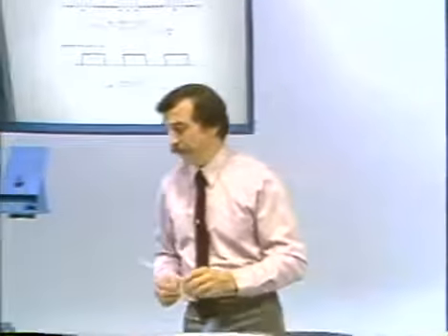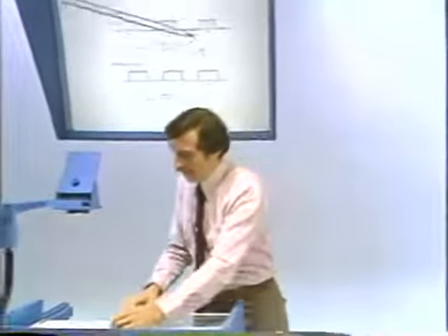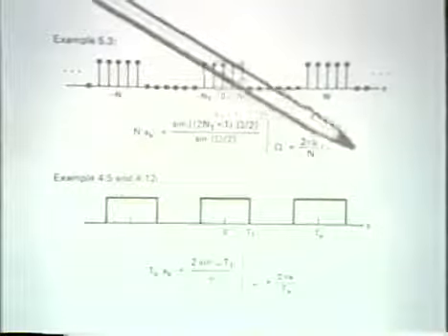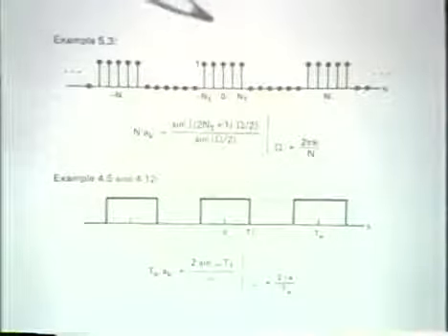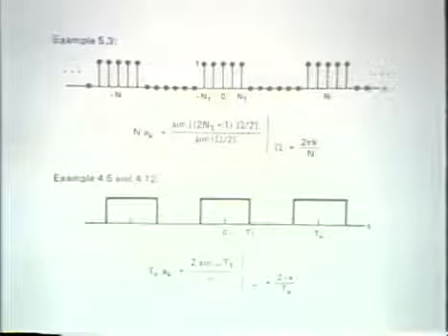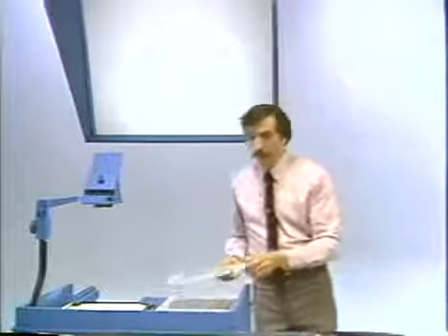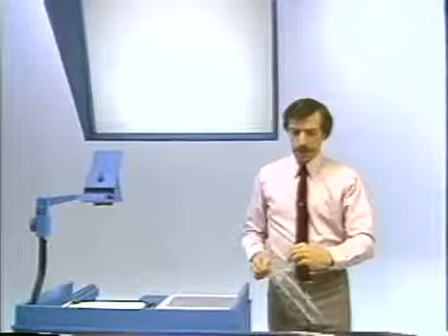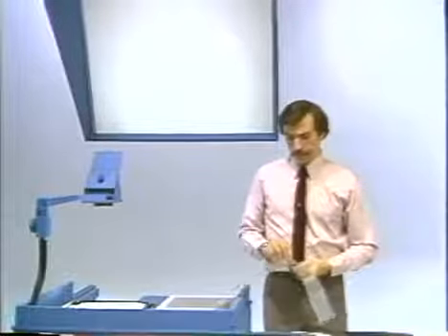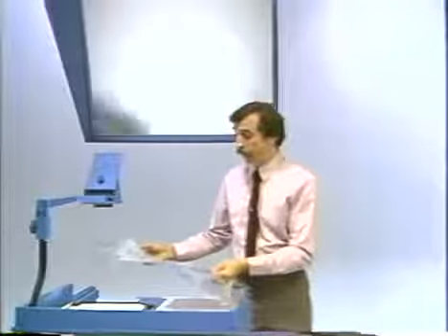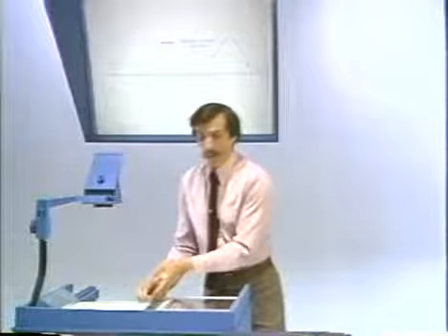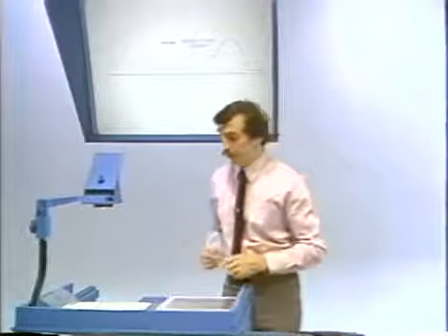So once again, if we look back at the algebraic expression, it's samples of the sine Nx over sine x function that represent the Fourier series coefficients of this periodic square wave. In the continuous time case, we used the concept of an envelope to represent the Fourier series coefficients, the notion that they were samples of an envelope, and that is the same notion that we'll be using in discrete time.